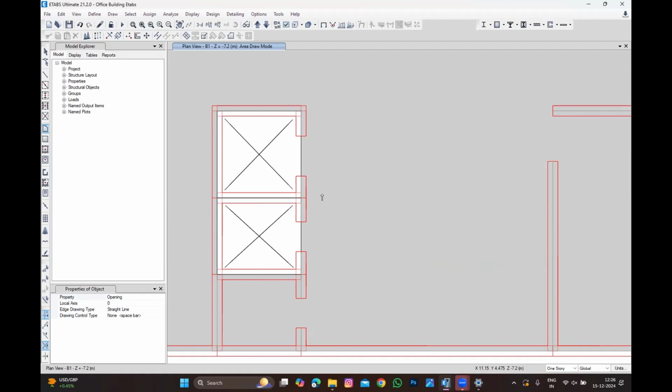If you look at it in practice, for the continuous beam, the top reinforcement is always more when compared to the beam which is ending at a support. Sometimes you will have end top support reinforcement, but when compared to this, the extra top reinforcement at the support is always more when the beam is continuous. When the beam is continuous, it takes more reinforcement than the slab or beam which has the end support.